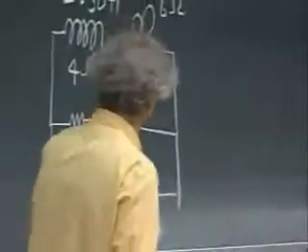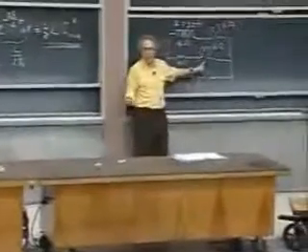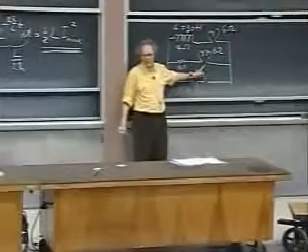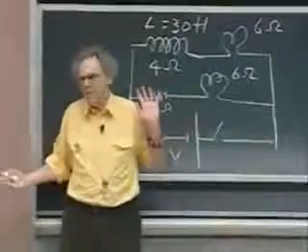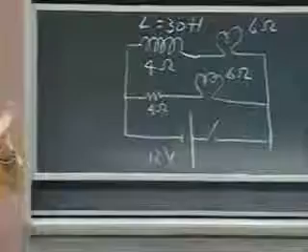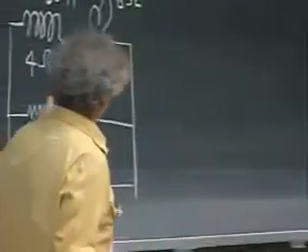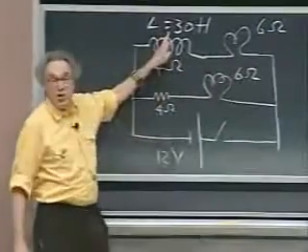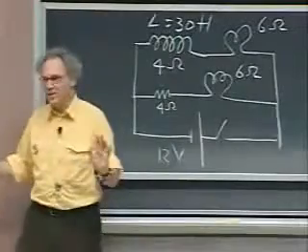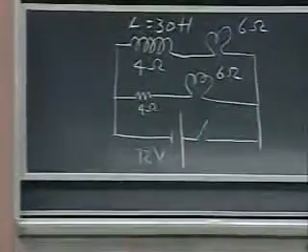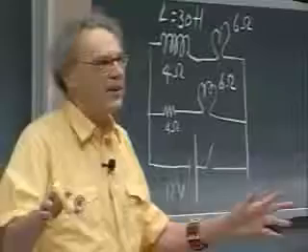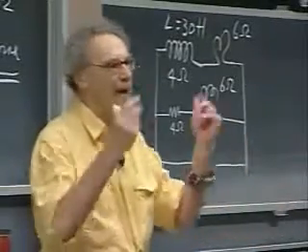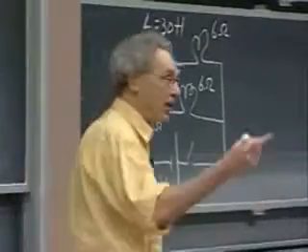You will see that this light bulb comes on almost instantaneously. There is no self-inductance in this loop. Well, maybe a few microhenry or even less. But in this loop here, there is this huge self-inductance. And so the self-inductance says, take it easy to the current, take it easy, just wait, and you will very slowly see that light bulb come on. And we can calculate how long it takes.